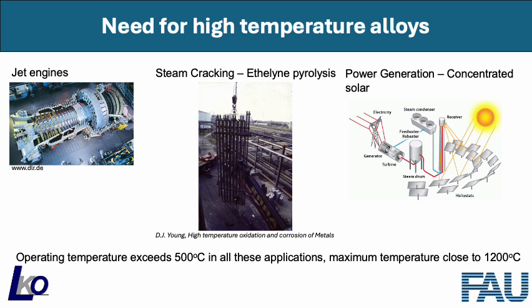For example, what concentrated solar power does is concentrate sunlight using these mirrors, which are called heliostats. When sunlight falls on them, it gets reflected and converged onto this tower called the receiver tower. Then the heat energy is collected and used to vaporize water, and the steam goes and turns the turbine, and we get electricity out of it.